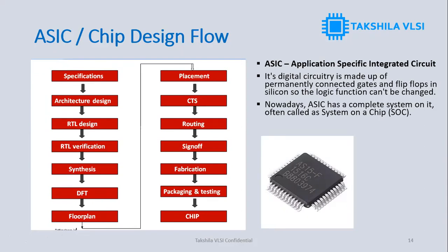So first of all, if you want to start any chip manufacturing or designing of a chip, you need some specifications. So what kind of specifications? Specifications like area, how much should be the area of a chip, clock, how many clocks or what frequency, right? And how many input and output ports, what kind of logic modules, whether it is analog module or digital module,